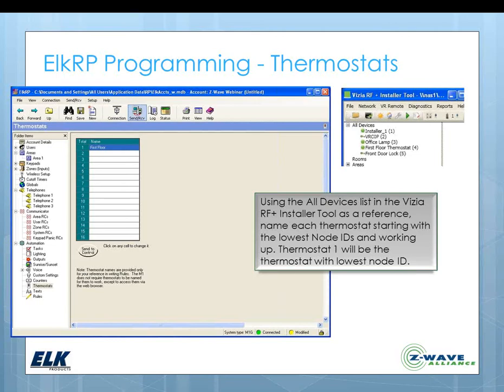I strongly discourage doing that. We do not recommend doing that at all. There's a lot of potential issues that can happen with mixing technologies, and Z-Wave is going to give you your lighting, thermostat, and lock capability. So if you're going to work with Z-Wave, we recommend that all of your lighting be Z-Wave, that you don't try to mix something in like X10 or one of the other lighting products that you could use the M1 with. But so we really do not recommend doing that. If you have any overlap of addressing, you're going to run into problems.